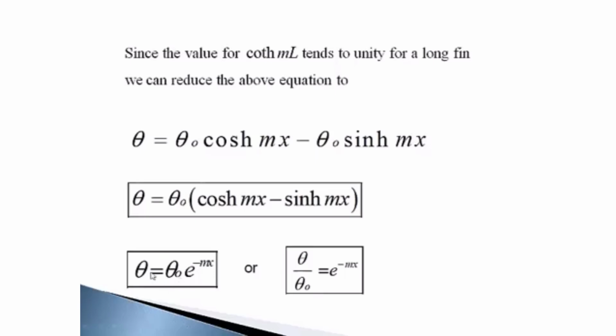But when it comes to some other point at some distance from the base of the fin, the temperature of the fin will be less. It cannot be 200. It might be like 180, 170. That temperature depends on the material. If it's a good thermal conductivity material, the temperature drop will be less.